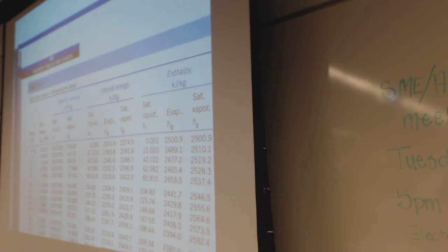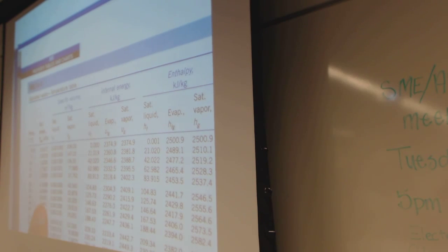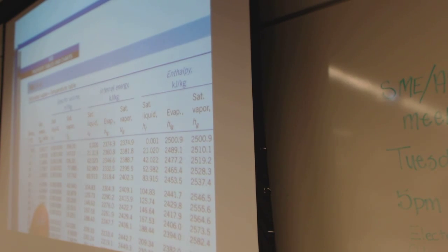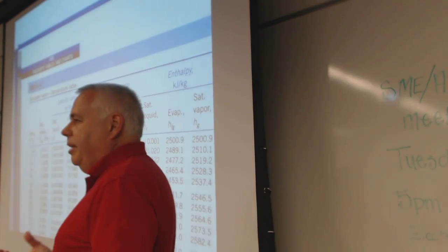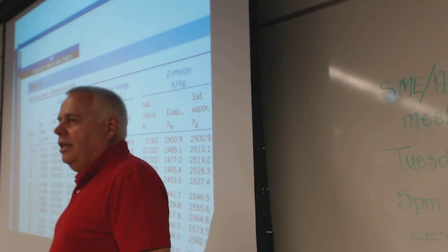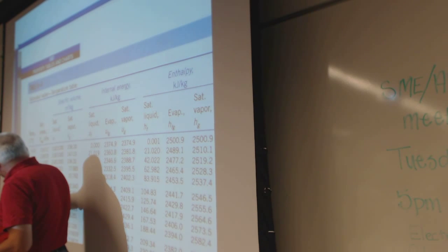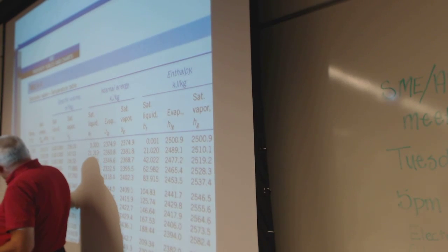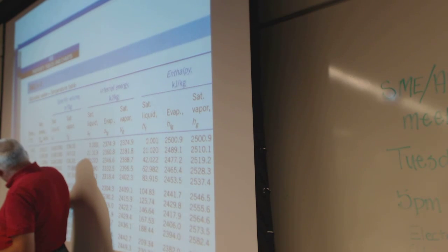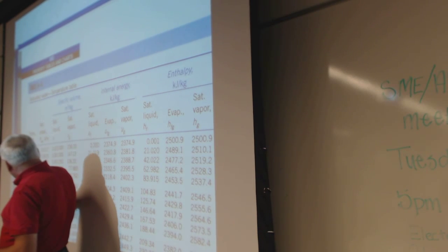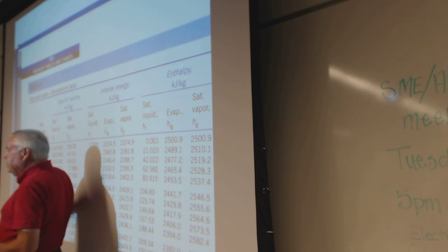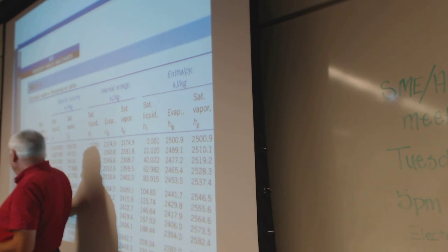Next question I had there is what is it if it's 6? And we could solve that one. I won't get into that, but basically, if we had a 6 kilopascal saturation pressure, the temperature would be somewhere above 35, probably something like 36-ish degrees C. That would be really high. It's not common that you actually see numbers that high.